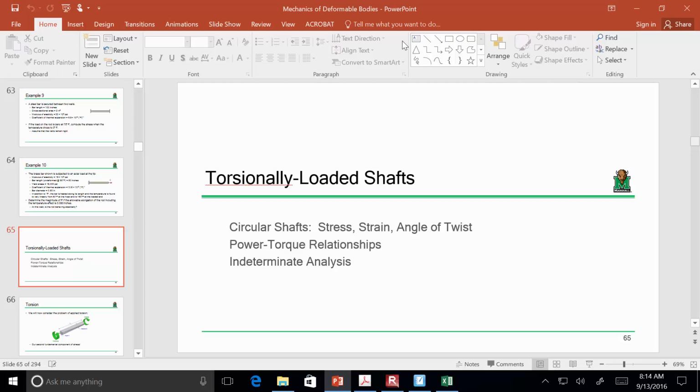So the deal with problem 2, you've got the same load supported by 3 cables, but the cables have different areas. So you have the same force on each cable, but it's all about what the stresses on each cable are, because stress is force divided by area. So while you might have the same force, you're going to have different stresses. Does that make sense?